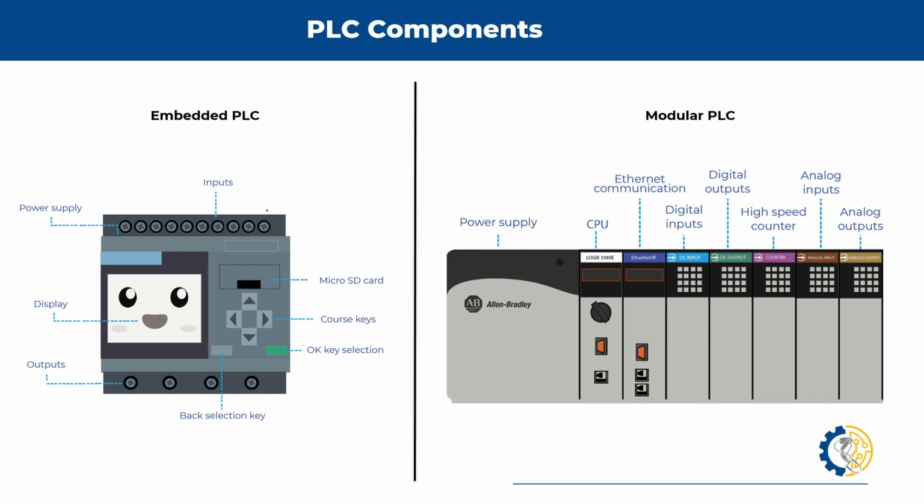And through the years, they know how to make things easier. But we also need to assign these instructions through predefined memories to be able to identify, well, this memory is going to be an input and this one is going to be an output. This one is going to be a digital input and this one is going to be an analog input.